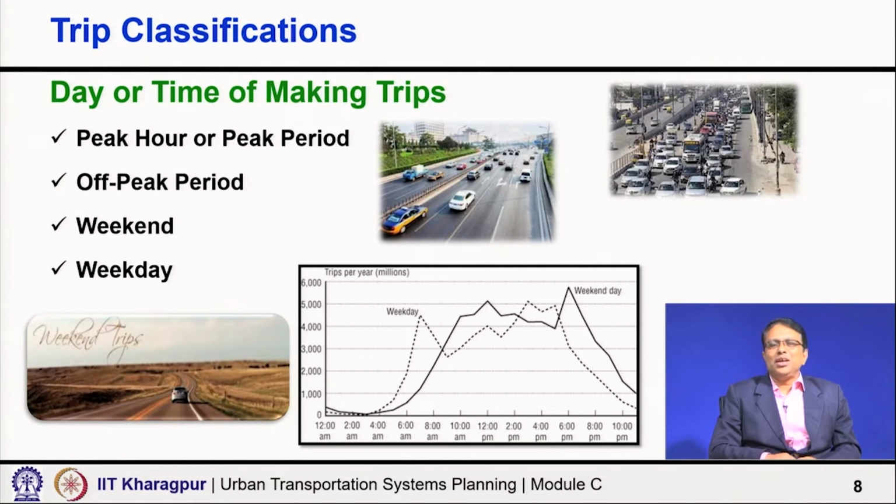So, if I consider daily, theoretically how many vehicles this road can take. Whatever is the road capacity per hour into 24, that is theoretically what I can consider the capacity. If you look, the demand will nowhere be near that value, but still why does this congestion happen? Because a larger share of trips happen only during the peak hour or peak period.